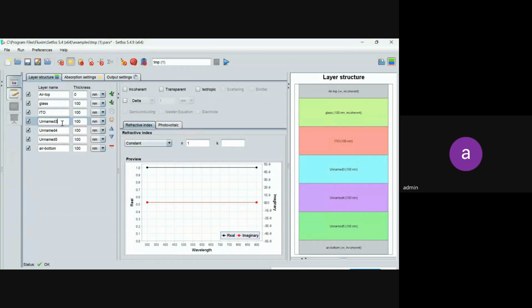And then the next layer I will define, as an example, PEDOT. PEDOT:PSS we can take. And then I will take the next layer, P3HT:PCBM, as an example. So this is our P3HT:PCBM layer, and then I want to define the next layer, which I can assume to be aluminum. We will define this layer's properties now. So once it is defined, then I have to define the thickness of my layers as well.